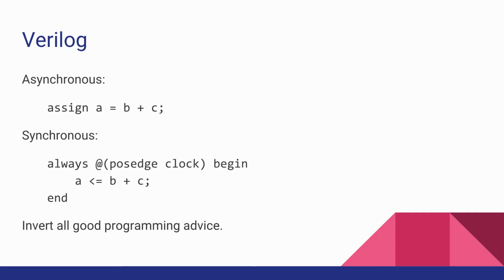But if this was a multiplier, then all of a sudden you become a little bit scared how many multipliers you have in the code. Exactly. If it was a multiply, and if they don't have hardware multipliers, then suddenly that blows up to who knows how many adders you need to actually make a multiply out of. Or if they have a hardware multiplier, then that uses up one of them.